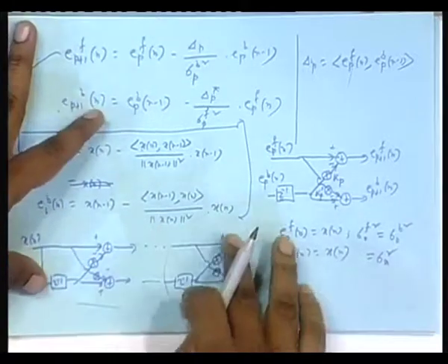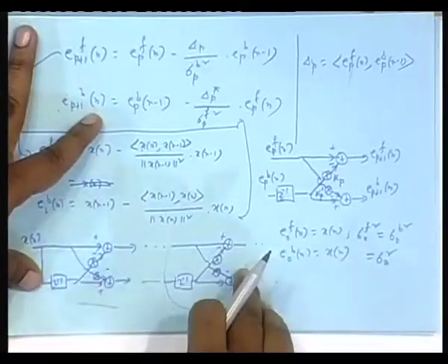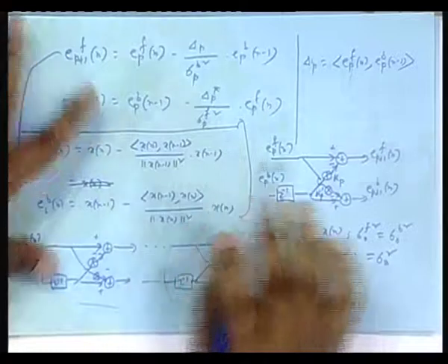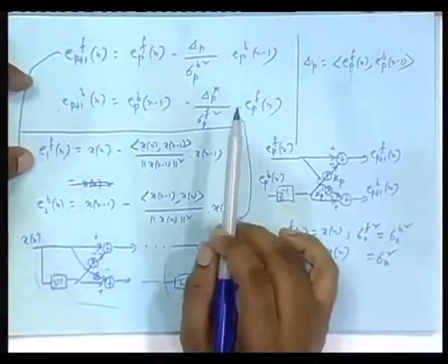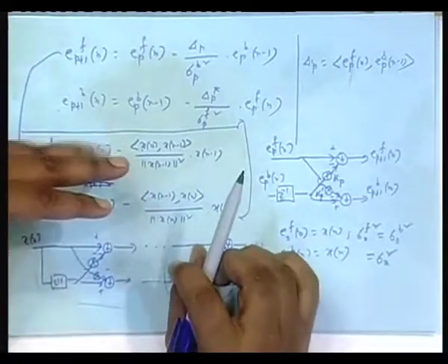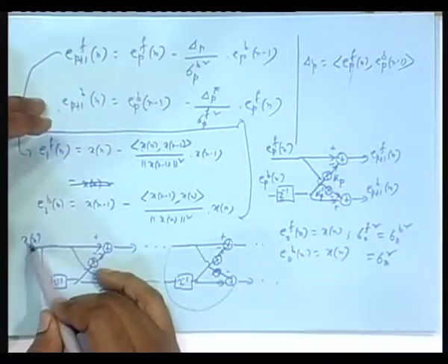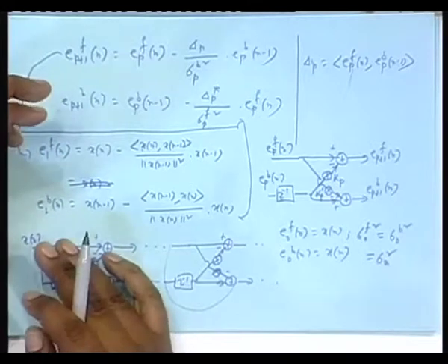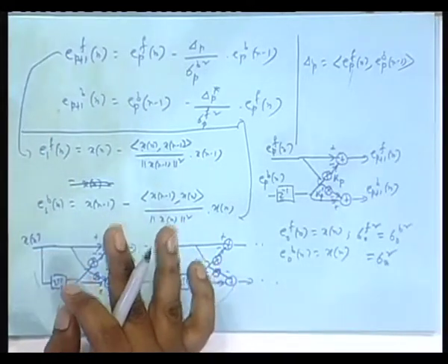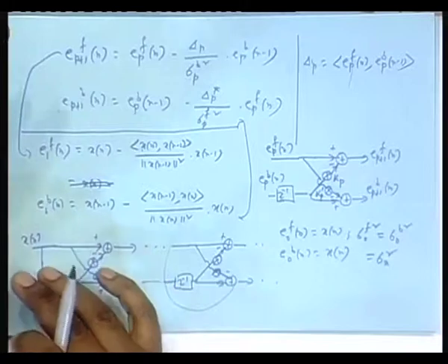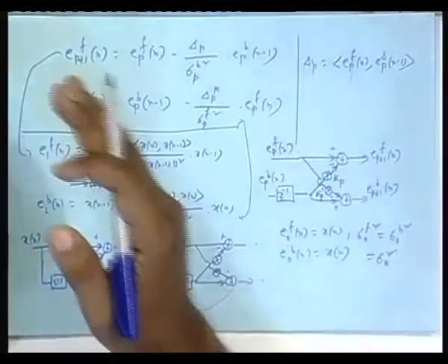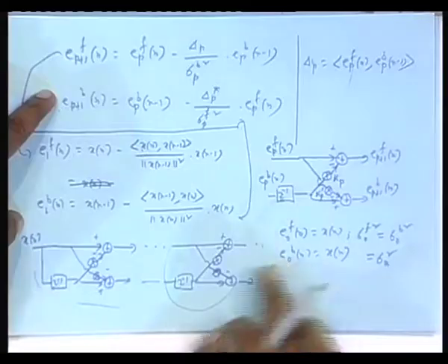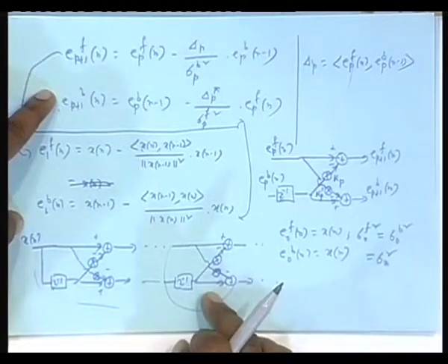So, what determines the lattice? Only the values of the coefficients. And what are the coefficients? The delta p's and the two variances, right. So, then we should try to develop computational ways, but what will be given? You will be given only this random process, or rather its correlation. I will be giving you the autocorrelation of a stationary zero mean process, with all its autocorrelation values for sufficient lags: 0 lag, 1 lag, 2 lag, a sufficient number of lags. You will be asked to construct this filter, that is, develop these multipliers with proper values.